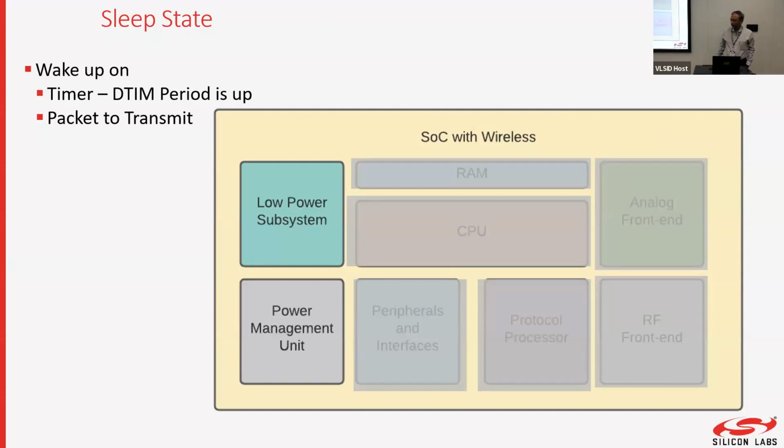The other is an accelerometer. The accelerometer measures the acceleration. If there's change in acceleration, you can sense that it's movement. And then that acceleration can be sensed as a piezoelectric thing, right? If you put acceleration on a piezoelectric sensor, the voltage changes. So you have a small circuit which samples voltage often and sees if it changes. That means that acceleration has changed. That means there's movement. So in any case, those are all handled by the low power subsystem based on what you want, and everything else is turned off.